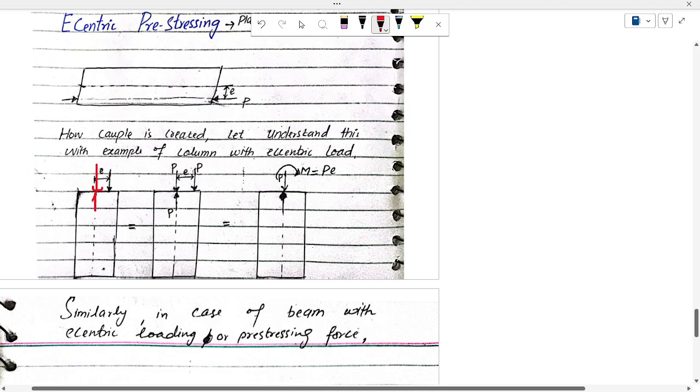After that, we replace these two forces, which cause a couple. So we replace this with a moment M equal to Pe, and this P remains.